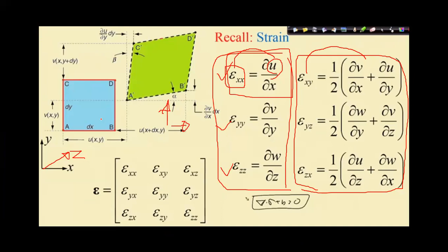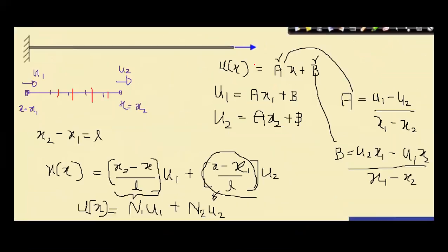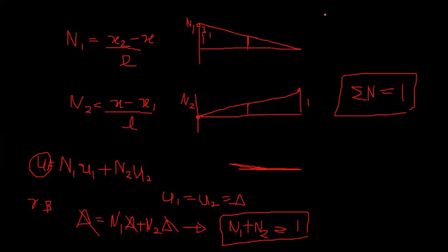This is for a 2D or 3D somewhere. So we only have one strain component. Why? We are working in a 1D problem, and things are only happening in the longitudinal direction, right? It's like a truss member, right? So du over dx. So this u is what? The displacement, not the strain energy. There are several u's, so don't be confused with that. This is displacement, okay?